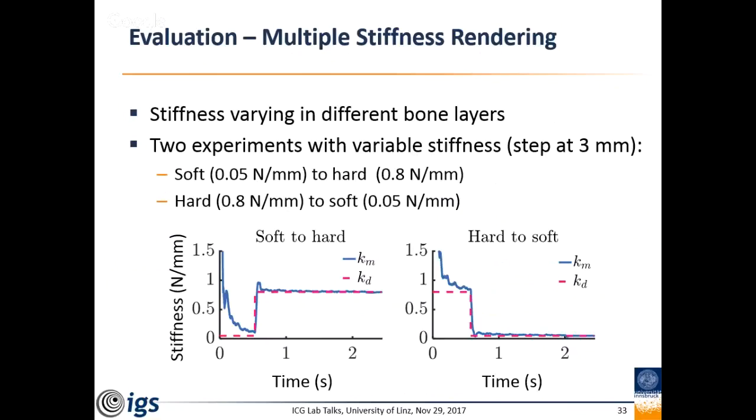But the bigger problem is at the start, because as I said, when we have a high offset force here, so it feels softer, the twisted string has to twist up. And for high forces, it has to do this actually a couple of rotations. That's why it takes a while. This is the disadvantage of the system.